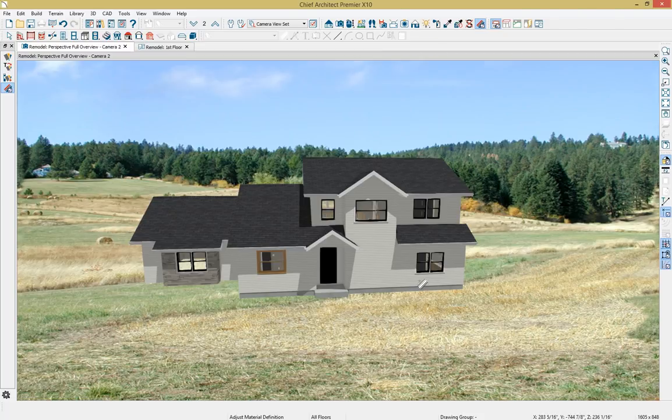And now I want to do something similar to match the color of my existing window with all of my new windows. So I'm going to use my material eyedropper, which allows me to grab a material in the plan. So I'm going to grab this black color, and I'm going to paste it onto the component of this window. And then I'm going to grab the white color that's on the outside edge of that window and paste it onto the window as well. So now that's still an existing window, but its paint colors match the new windows that I've placed.